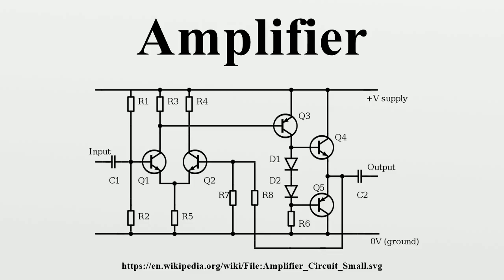Amplifier types. Amplifiers are described according to their input and output properties. They exhibit the property of gain, or multiplication factor, that relates the magnitude of the output signal to the input signal. The gain may be specified as the ratio of output voltage to input voltage, output power to input power, or some combination of current, voltage, and power. In many cases, with input and output in the same unit, gain is unitless.